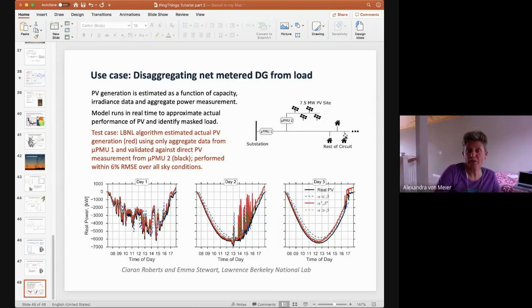Because what if there were a disturbance event that caused this solar generation to trip offline suddenly? In that moment, they would become painfully aware of all the load that had been offset by it, and they would have to be prepared for that contingency to supply that load from some other generation. So system operators need to know their risk exposure to the loss of solar.